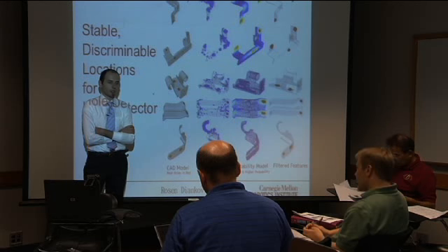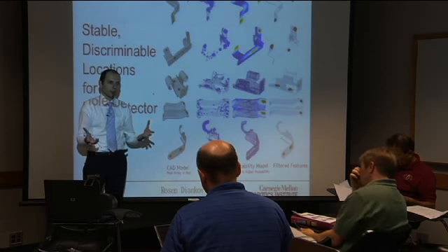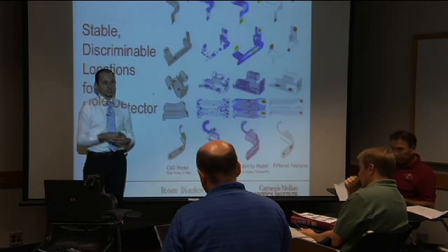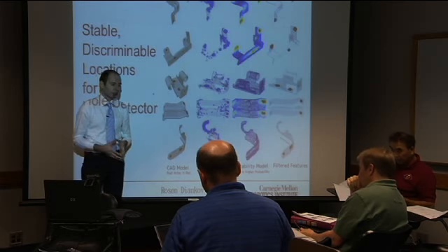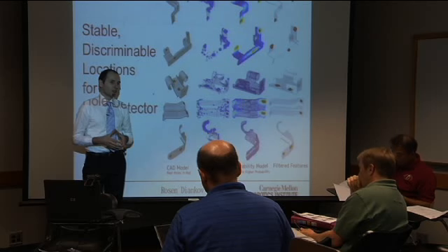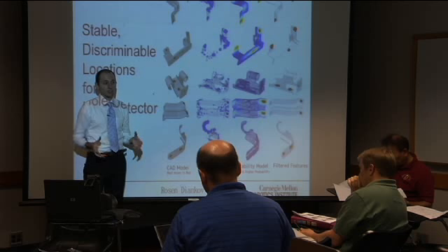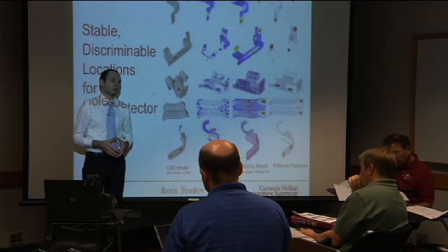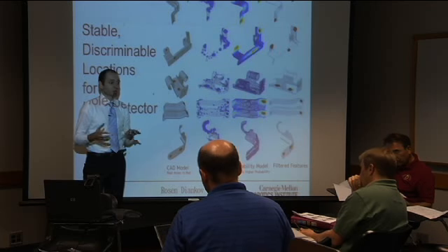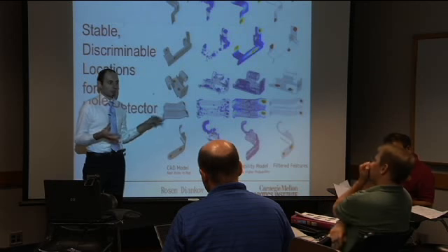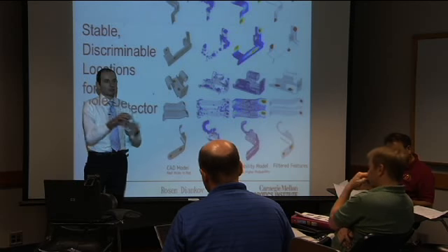In fact, just to add on to that, a lot of people use dynamic simulators to get this predictive behavior inside their planners. Right? But I would say that today, especially when friction gets involved and all these uncertainties, we really don't have a good dynamic simulator for robotics. Which is one of the things that are preventing us from moving into this step. But if there is ever a next step for this type of manipulation framework, it would be to add that slowly.